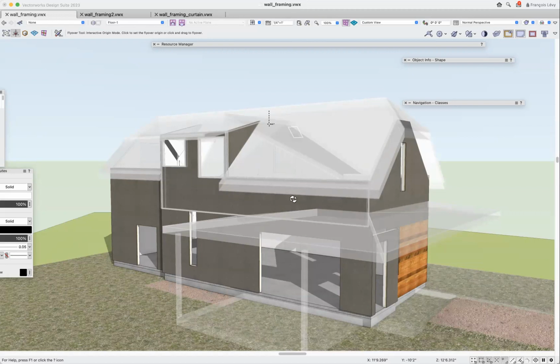So I was sort of faced with having to try to quantify what the lumber cost differential would be if I advance frame a project versus traditional framing. So, you know, you would think, well, if I have fewer studs, but the studs are more expensive, it's probably going to be a wash. But you really need to figure that out in some cases.